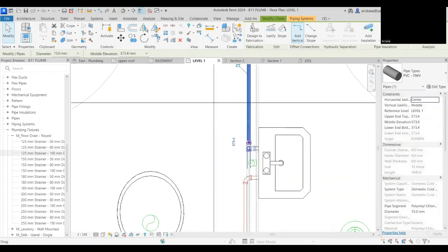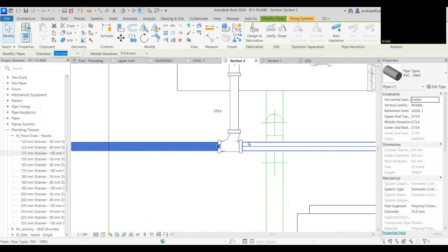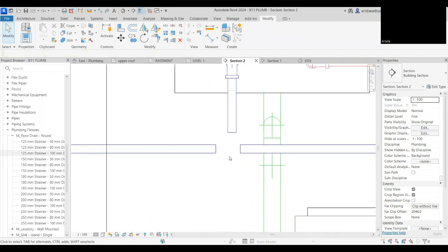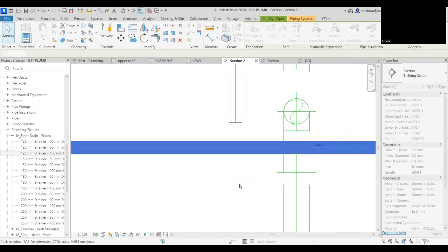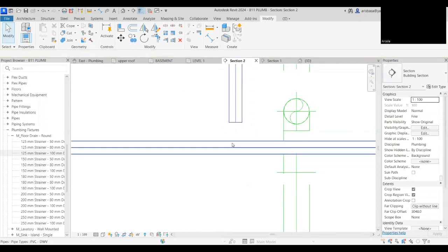Now, this is not yet correct, right? Where is that view? See, it should be a T, right? Not like that. So what we'll do is we'll select this and we can actually delete that. Okay. And this can be connected to this pipe. You just drag it and it will connect. It will not put a coupling. It will just be as a straight one. Now, this guy can go here using our same command. Click this and click that. Boom. Now correct. The water will go there.